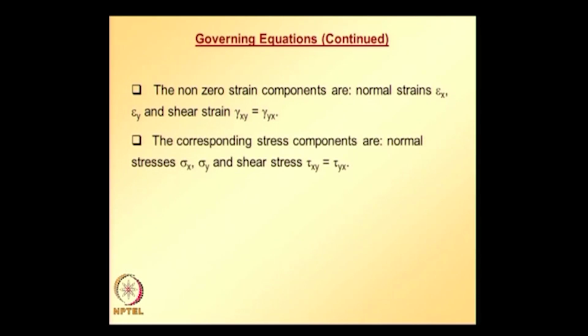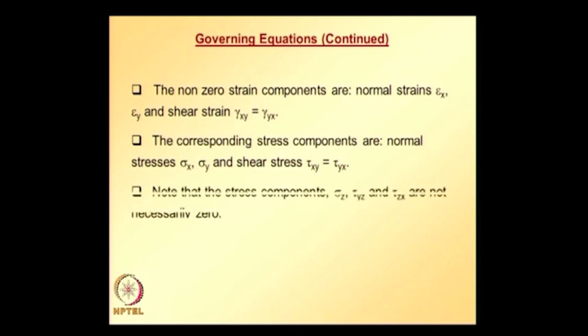The corresponding stress components are normal stresses and shear stress. Again, out of plane strain components are 0 for the plane strain case, but out of plane stress components are not necessarily 0. Note that stress components sigma z, tau yz and tau zx are not necessarily 0.